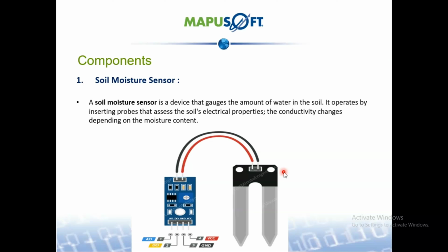If the moisture level is below the set threshold value, then the system activates the water pump to irrigate the plants. The control logic, which decides when to water the plant, is simulated in the RTOS on a host machine, allowing the developer to test and fine-tune the irrigation process.